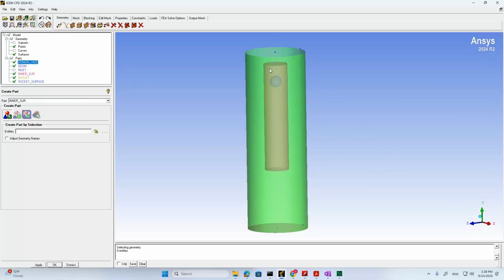So I'm not going to apply any real boundary condition to this surface of the smaller cylinder because it's not really a physical boundary. Okay, I do not know any physical condition along this boundary. It's only a means to separate my computational domain. So there is no need to define those surfaces of the smaller cylinder with many different names. Okay, it's just one whole piece.